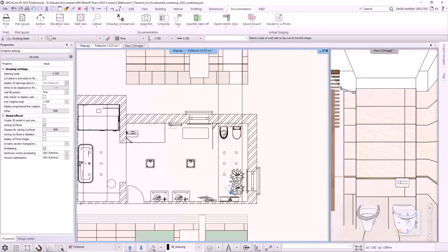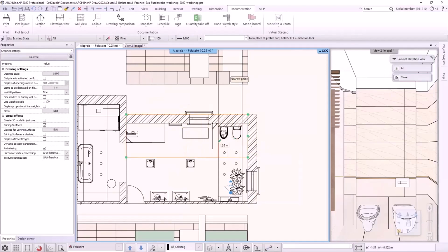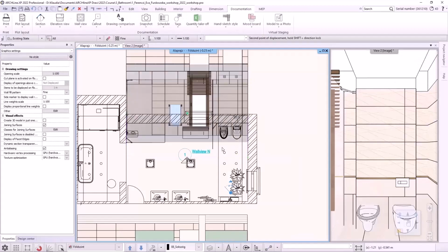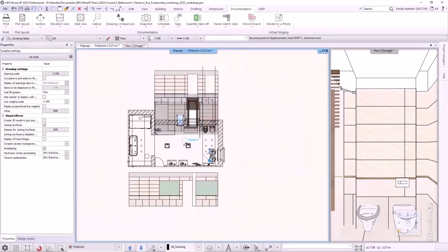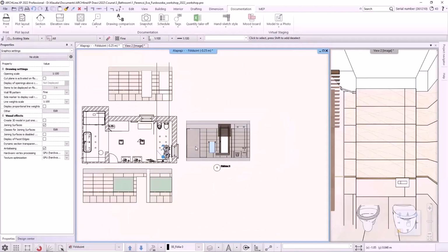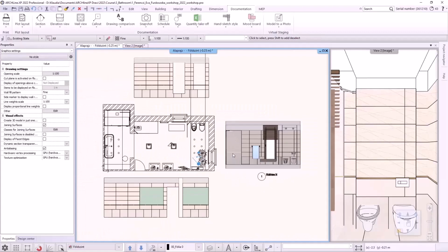I click on the wall and then use the arrow to set the direction of the view. A blue rectangle appears, allowing me to set the area which will be on the wall view. I press Enter to accept it. The wall view is created and I'll place it on the floor plan. The wall view is a group. It can be dimensioned by entering in it.